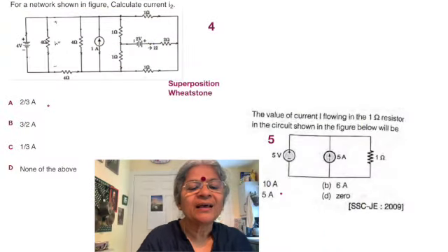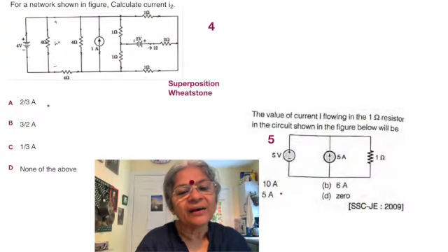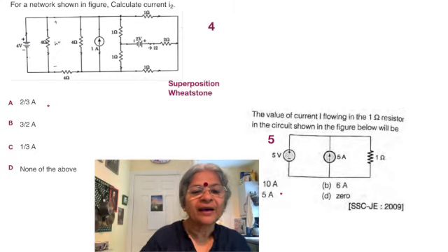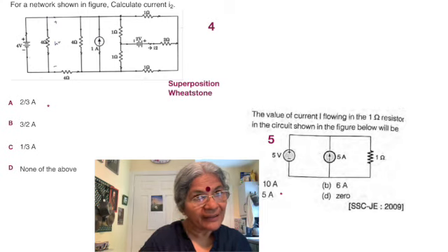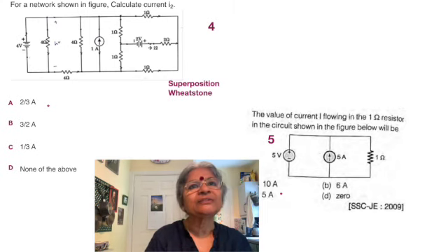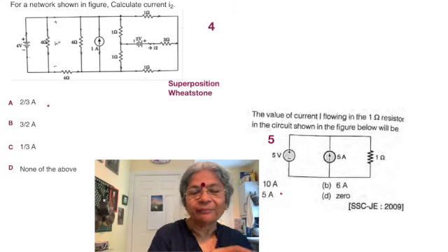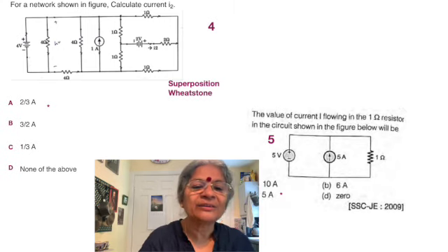So in total we have the 2 volt source and a 2 ohm resistor, and we have half and half resistors. There is 1 and 1 in parallel to create a half, and then in series with the other 1 and 1 in parallel, so another half. So in total we have 3 ohms resistance.